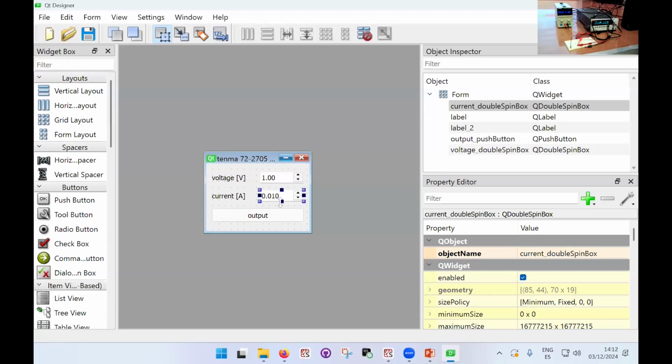So it works, it turns on around 2 volts and it has a maximum rating of 30 milliamps. So I want to make sure that I never exceed 30 milliamps because otherwise it will probably get damaged. So whenever I do the demonstration here, I'll probably set the maximum current as 30 milliamps. And if I do that, as soon as I turn it on, I can increase the voltage as much as I want, but the power supply itself is designed so it never exceeds 30 milliamps. So you'll see that in action very soon.